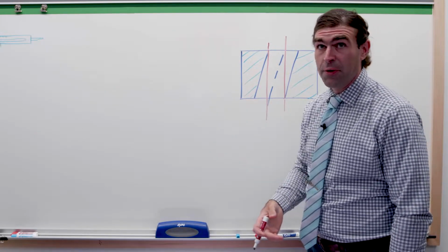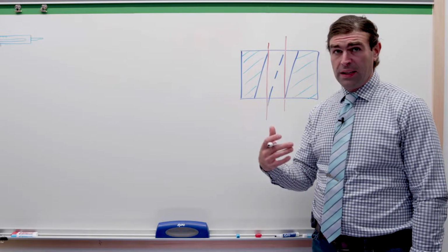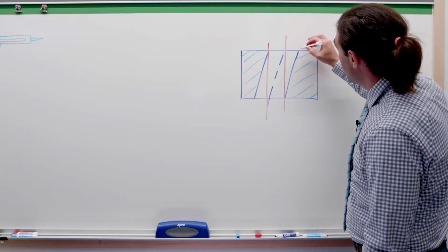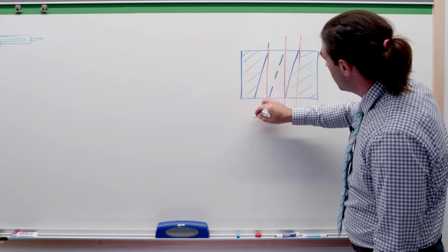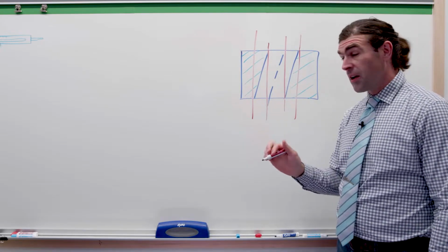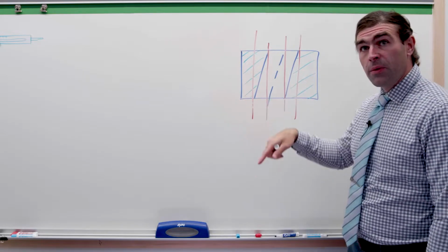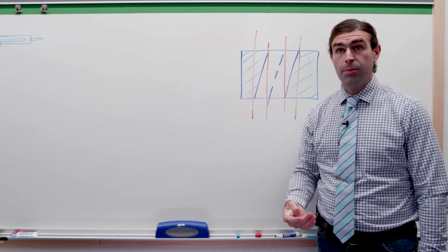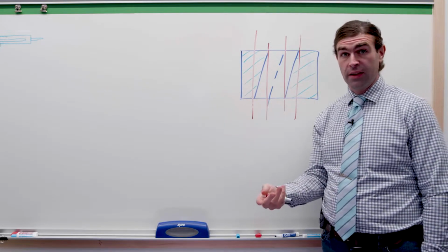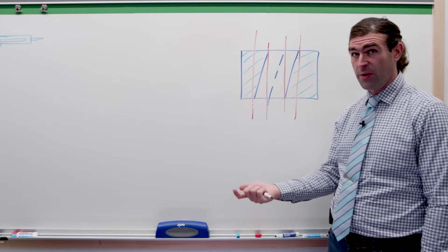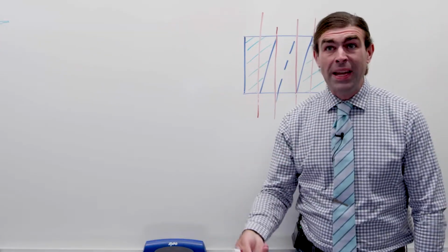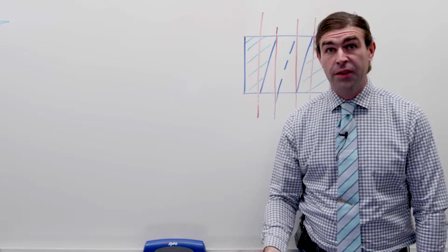Now, a position tolerance is going to be related to something. When we're thinking about how parts fit together, this matters. The outer boundary is going to be the most room the feature can take up. So we want to consider this when we're thinking about wall thickness, right? So it's not going to be readily apparent, and I'll give you an example later, how much wall thickness you're going to have just by looking at the size tolerance and the position tolerance. So this maximum room it can take up is dependent on both the size and the geometric tolerance.